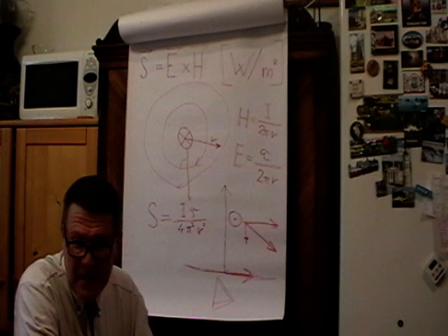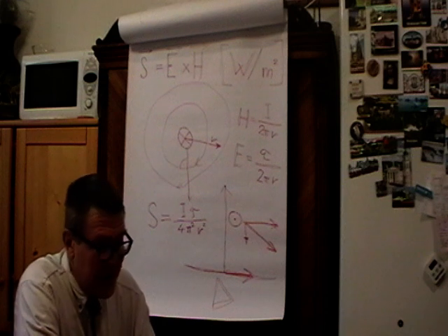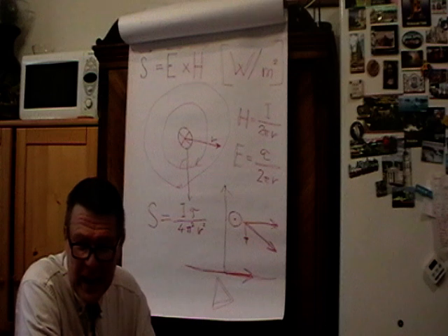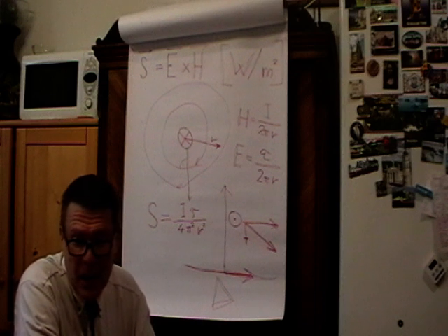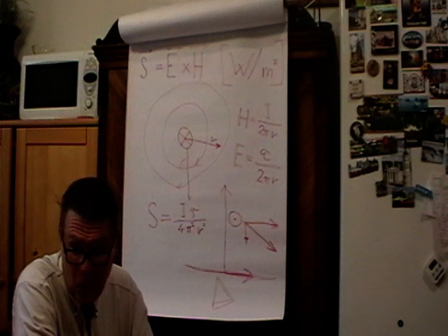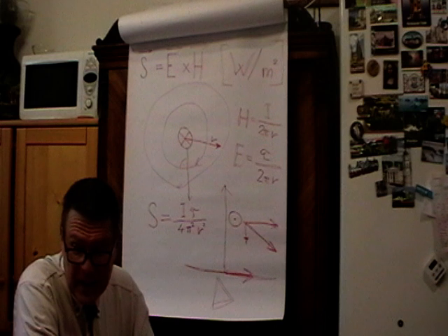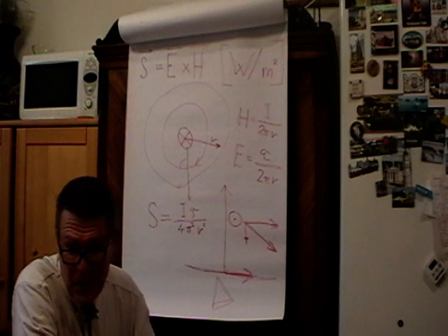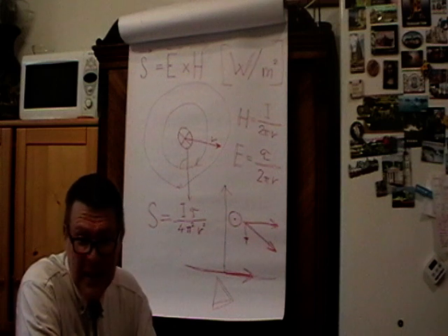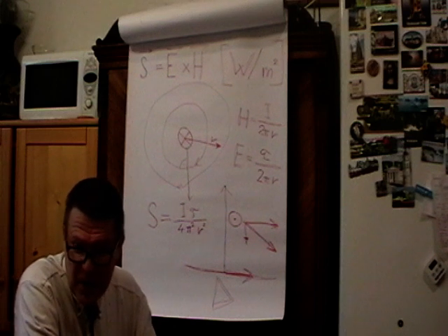It is normal if your voltage is within plus minus 10% limits. So for the nominal value of 230 volts, you can get 23 volts more or less, and it's still okay. And this depends on the consumption in the network.